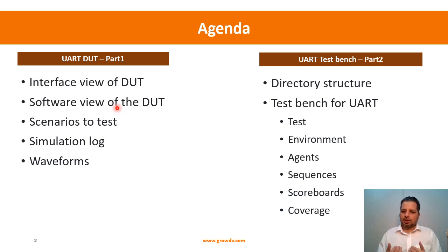Now that we have bought these two, because that is the primary business case of the UVM that we talked about, right? That is, we can buy various verification components, either from a third party vendor, or from an internal team. Buy or borrow, right? Borrow it from an internal team and put it together, and we can reuse it and build our test bench on top of it. So for this session, the way we are going to do it is, we say, yes, we have a UART agent and an APB agent, we take those two agents and then build our UVM test bench on top. That is what we are going to do.